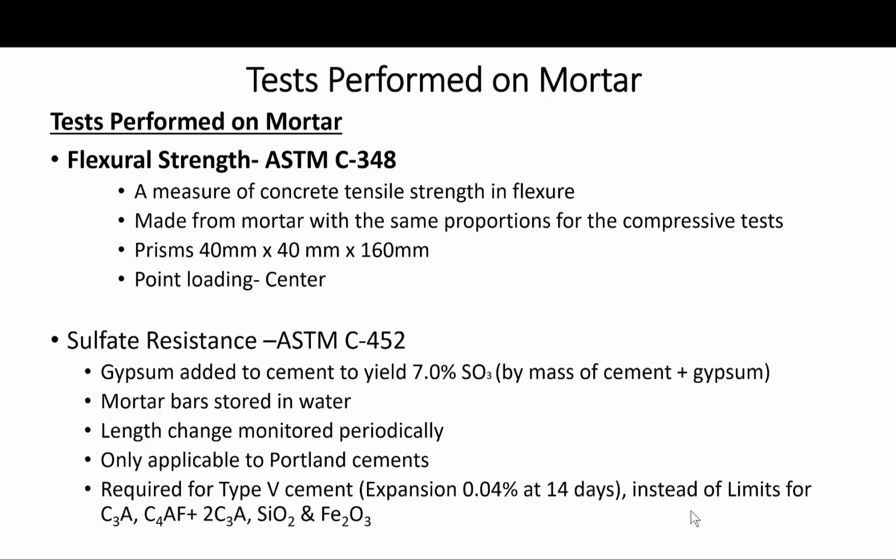It must be remembered, though, that the strengths of mortar as determined by these tests cannot be related directly to the strengths of concrete made with the same cement. So the strength tests on mortars serve primarily as quality control tests. Again, remember this: quality control tests.